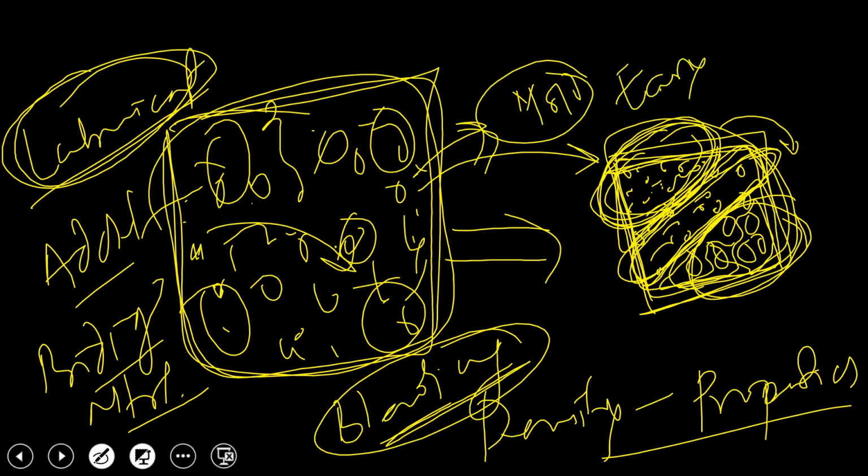There has to be minimum friction between the mold surface and powders, because that friction is going to impact the life of the mold. And also, if that friction is minimum, that compaction would be better and density would be better. That is the role that lubricants play.